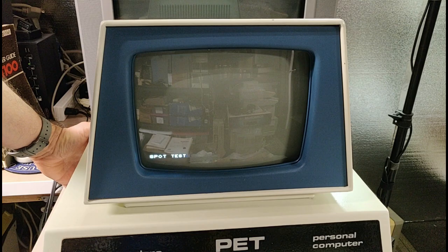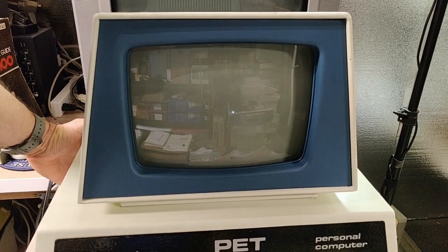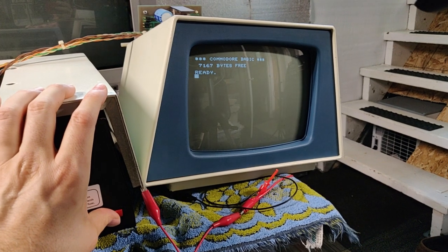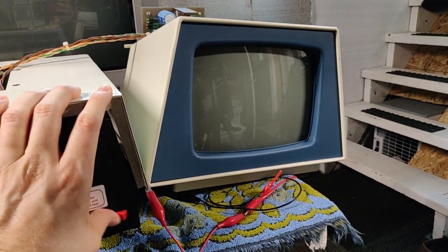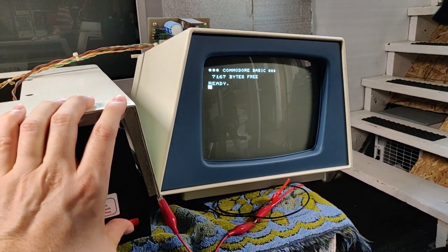Now I told Adrian about my fix, and he tried to install a similar fix on his monitor. This is the unmodified Adrian's monitor spot. As you are going to see, it appears earlier than on my own, and it's brighter too. On Adrian's monitor, however, the zener mod didn't seem to have any effect, even after he bought new zeners from DigiKey, since I warned him that some low-quality ones are unsuitable for this modification.